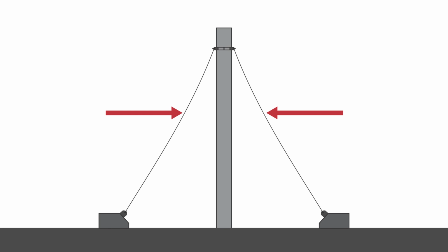A set of guy wires is referencing all of the guy wires attaching to a given elevation on the stack. Each guy wire is attached to the stack at one end and then to a deadman at the other end. A deadman refers to an anchor point for the guy wire. Typically, this would be a concrete block at grade, but it could be elevated and attached to another structure.